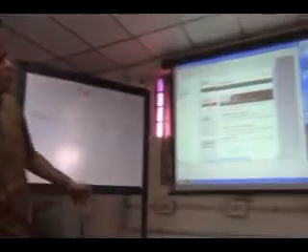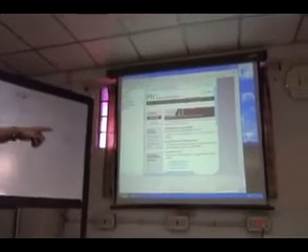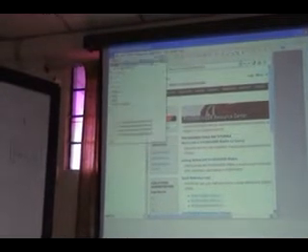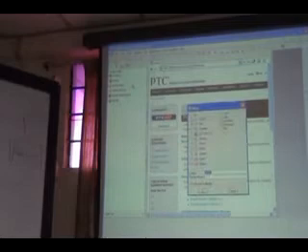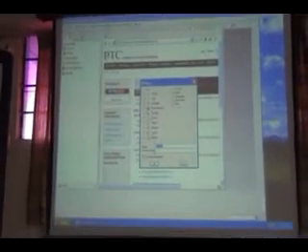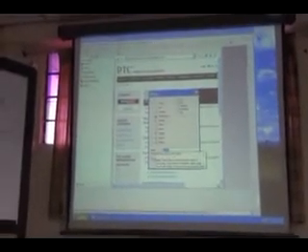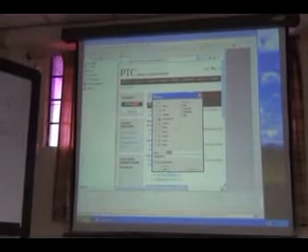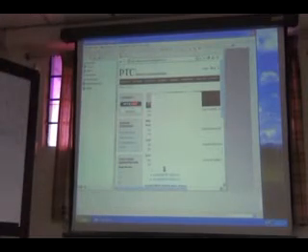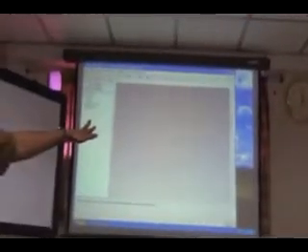First of all, how to create the model in a design package. You will be studying this again in your further semesters. We will see it here. This is a Pro Engineer environment. I am creating a new file. You see, I have so many modules. The part I'm going to create is a 3D part. The name of the part it is asking, so I'm giving it. This is the three-dimensional part model environment you are going to have.